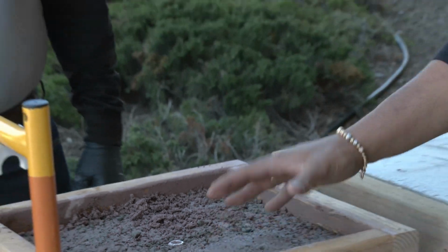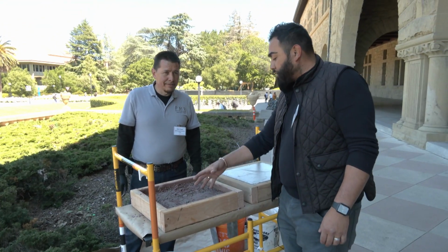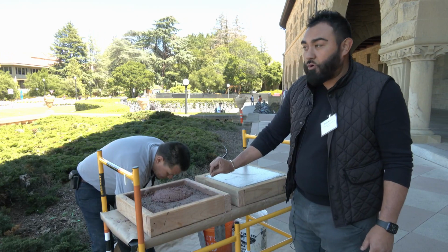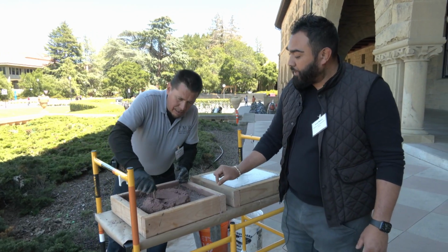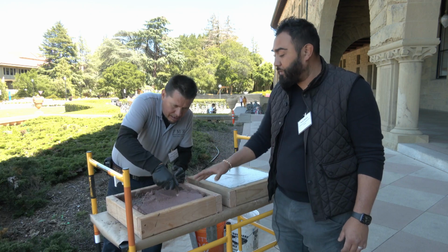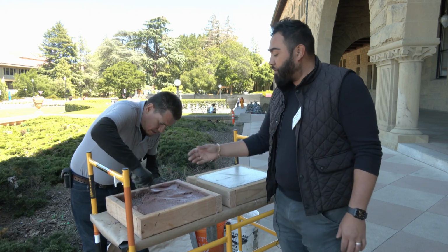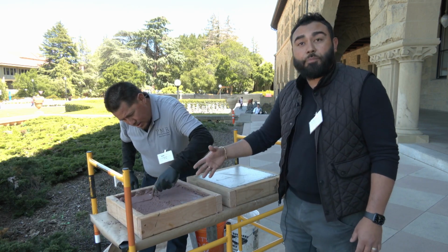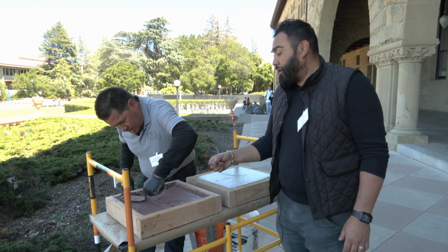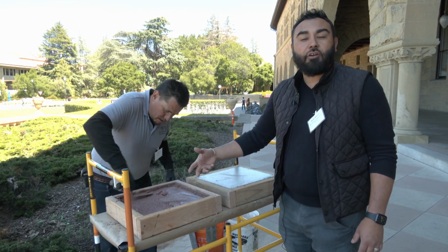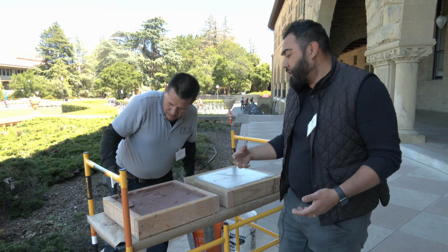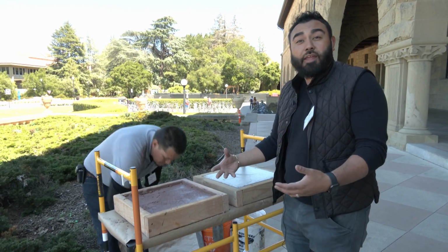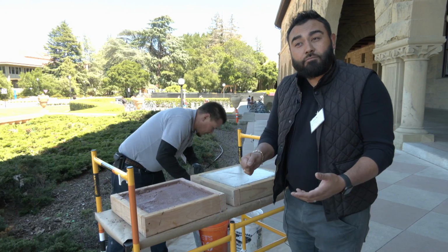So we do a 4-inch concrete here, and then Juan is going to start installing the color. The color is about 3/4 up to 1 inch. It gets spread out. We do a thin layer first to make sure we get nice bonding. Once he does that, he comes back and taps it, and then he's going to screed it. And the most interesting part is we're going to broadcast the aggregate. We use 2 different sizes to give it a natural finish. And once the aggregate has been broadcast, he's going to trowel it so it's nice and sealed.